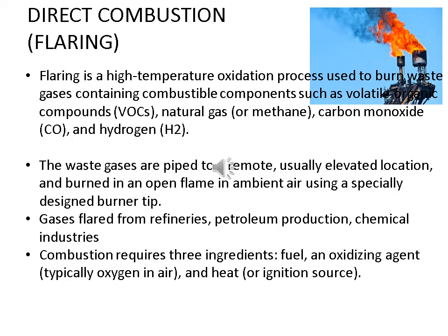This is mainly used in industries like refineries, petroleum production areas, and chemical industries. The working principle: the waste gas is piped to an elevated location and burned in an open flame in ambient air using a specially designed burner tip. The ingredients required for this combustion process are a fuel, an oxidizing agent, that is oxygen here, and a source of heat.